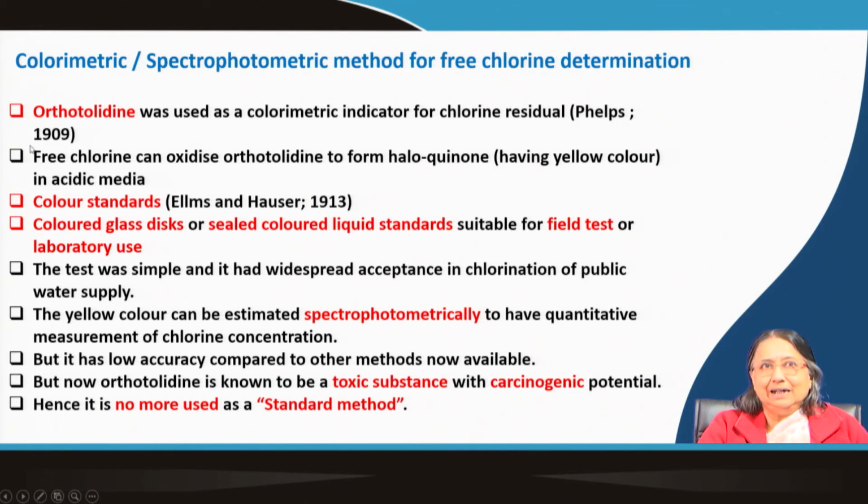You see the year 1909. So, Phelps, very old method. Free chlorine can oxidize orthotoluidine to form a haloquinone. Quinone, I told that sometimes it has color, having yellow color in acidic media. Okay, free chlorine can do this. Color standards, this is done by this color standard.